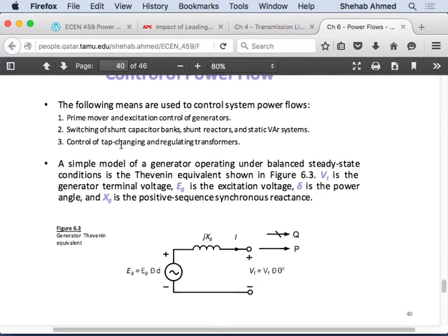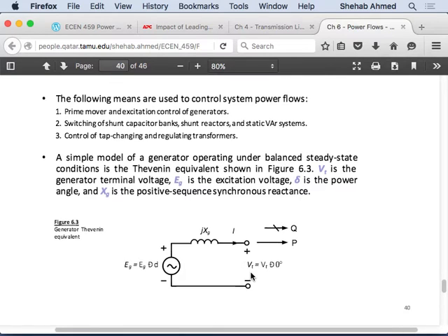So let's look at the simple equivalent circuit of a generator connected to a voltage bus. And I think the way it's referred to in power system terminology, and in 338, Dr. Aitam probably talked to you about an infinite bus, right? Did you hear the word infinite bus before? What does infinite bus mean? Infinite bus means just a big system, a big system that has 100 generators, for example, that are synchronized. All these generators are at similar voltage and running at similar angles, right? Your small new generator coming in to synchronize is not going to affect all of these.